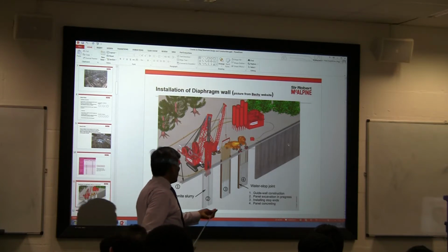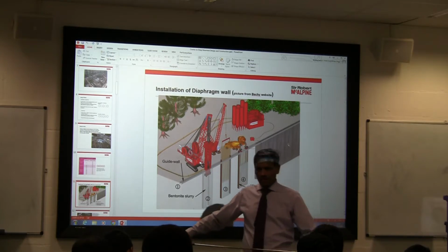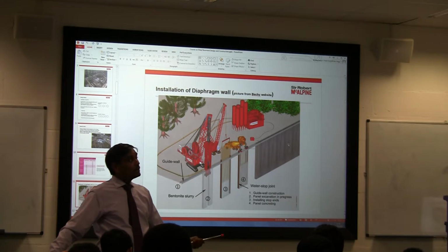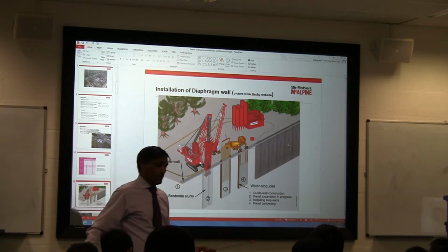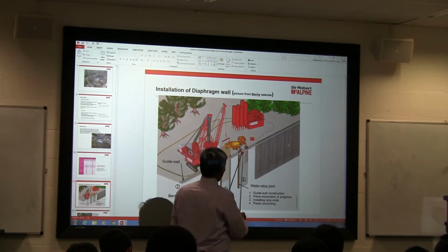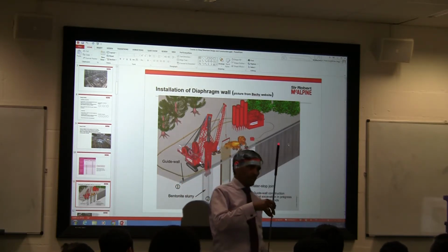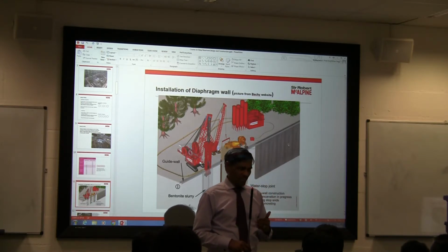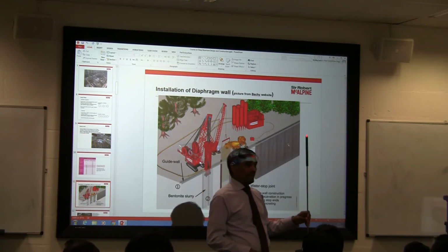Now, when should I use the diaphragm wall? When do you think I should use the diaphragm wall? Yeah? Tunneling structures. Yeah, absolutely, yeah. And also, if this is very deep, when you are boring, it's very important, when you are working in a water strata, it's very difficult to see how you are going to get an interlock.